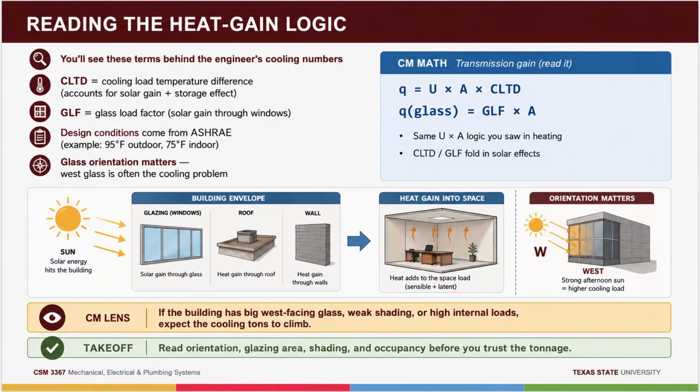On the handful of freak afternoons above it, the building drifts a degree or two, and that is by design, because chasing the last degree of the record heat wave means paying for capacity that sits idle 8,758 hours a year and, as the next slide will show, actually makes the building less comfortable the rest of the time.